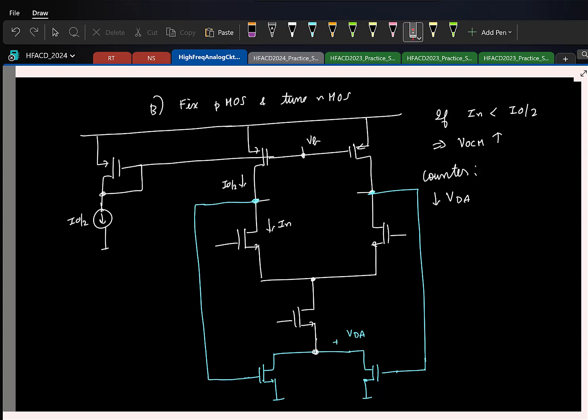So once again, you know that this voltage VDA, do you think you want it to be a large voltage or a small voltage? You want it to be really small. So in which region do you think these transistors are operating in? I mean, this is the drain voltage. You ideally want it to be really small. So in which region? Linear. Okay. So this will be operating in linear region, mostly like a resistor. Okay. So that is something to note. Let me call, I don't know, how do we call this? Let's say MA. So MA operates in linear region.